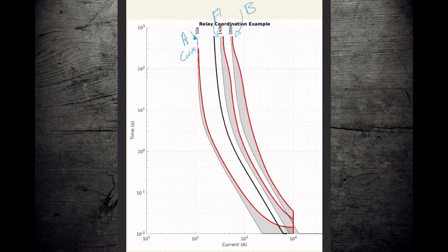Now in this case, I've got our recloser pretending to be K-speed fuses. We don't have to do that. We can make our recloser pretend to do anything we want. So now you'll also notice that up here, our B curve, which is emulating a 200K, doesn't have a coordination line.